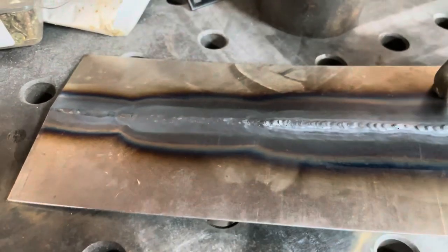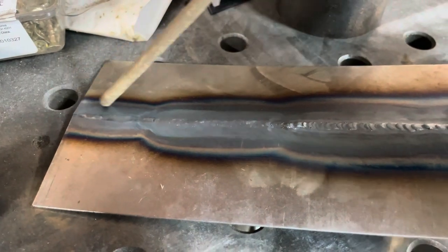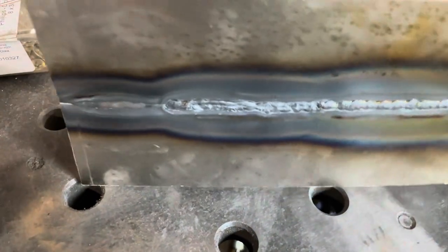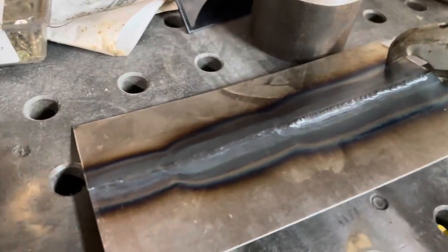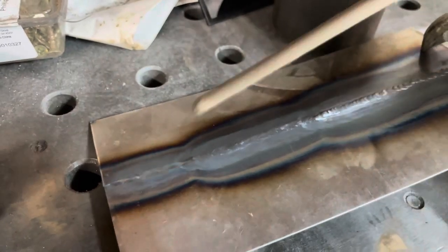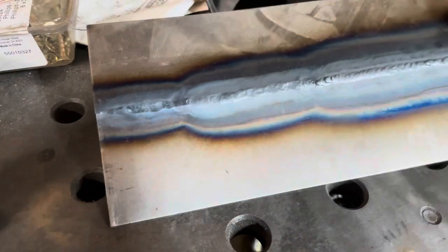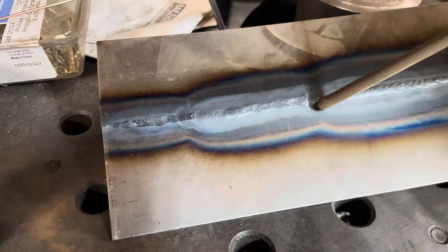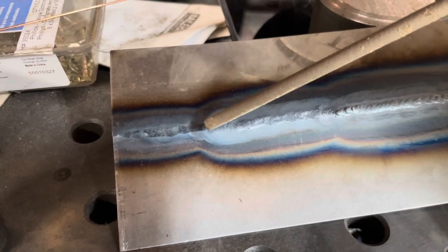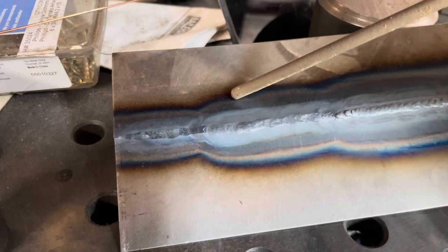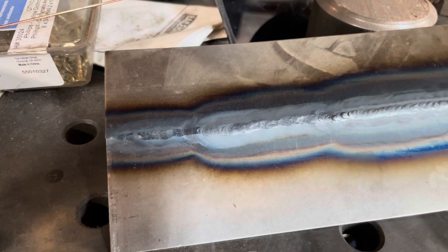So in the beginning, all I was doing was a fusion. This is just a fusion. And you can see I got 100% penetration. That fusion, I did not have to worry about the filler metal cooling the puddle off, so my heat affected zone is smaller. But as I started adding filler in this section, I still got a complete fusion and 100% weld, but I had to take more time. And with more time, the mass of this panel could pull more heat away. And that's an example of the thermal conductivity.